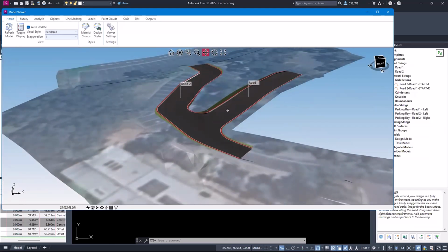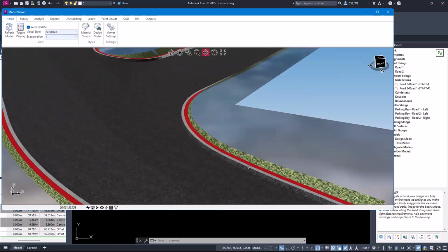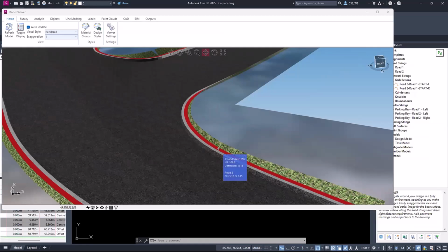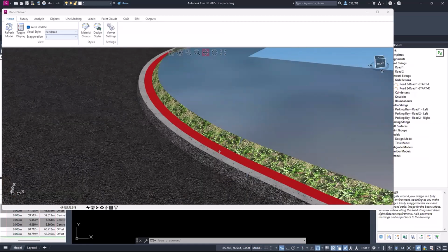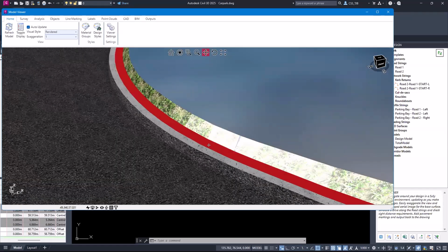That model then, and to be honest, when I built the road template, I think I got the codes backwards. I suspect I actually called it BK and TK instead of TK and BK. Hence why this has come up red. That's just operator error from me. I can see it.